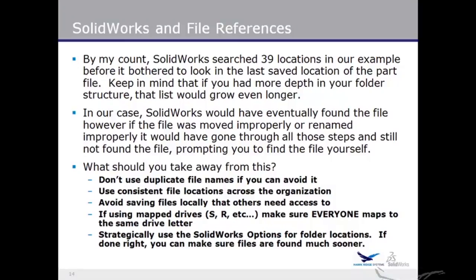So if you go to the SolidWorks options and you add the very top level folder of where your toolbox files are stored on the network in everybody's computer, one of the first locations that gets searched for references will be that toolbox folder. And as it does its recursive searching, it's pretty much guaranteed it's going to find the right folder that it's looking for. So instead of pulling toolbox files off local drives and having a whole big mess of things, you've got everybody pointed to that drive and you're strategically using this to your advantage.